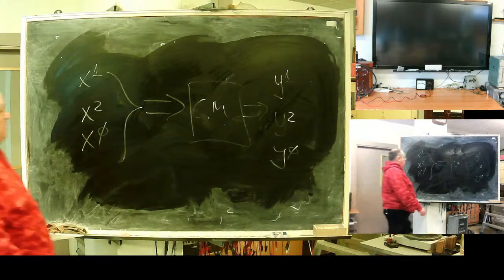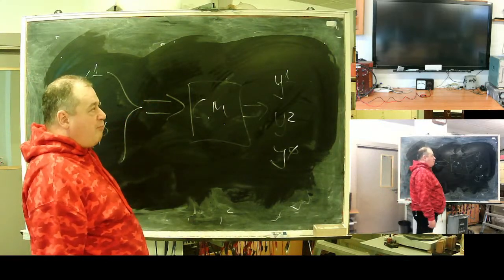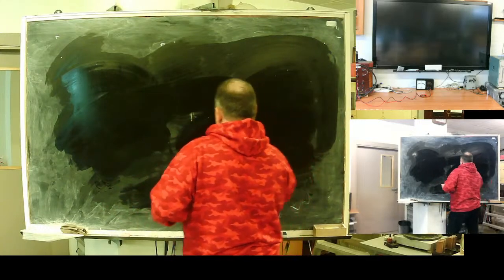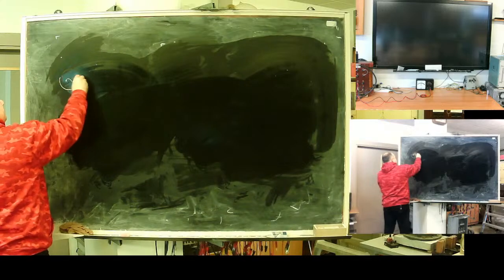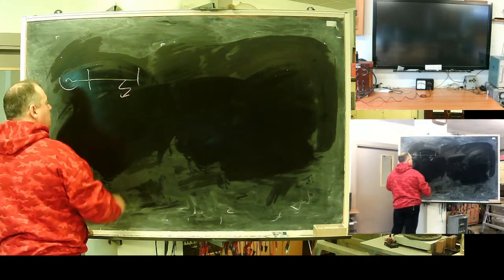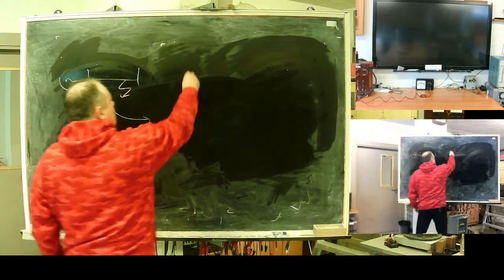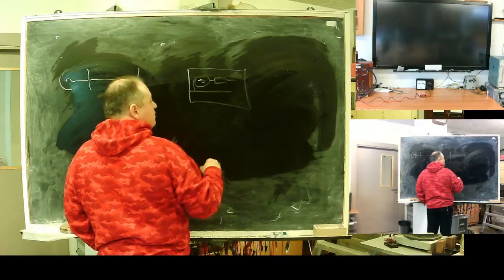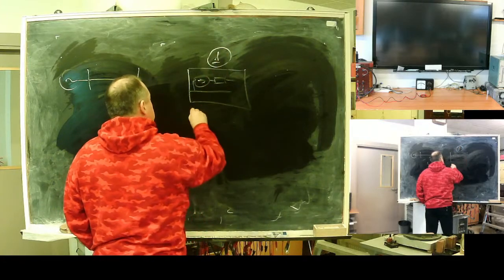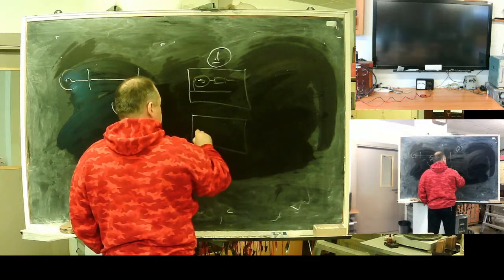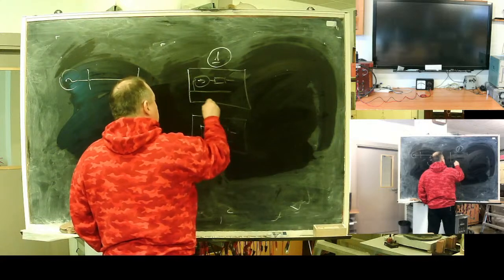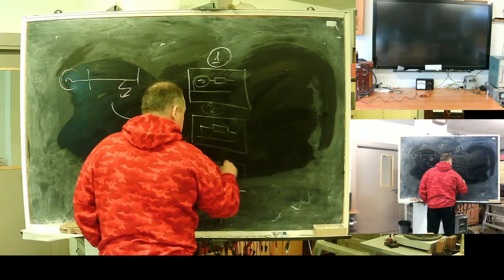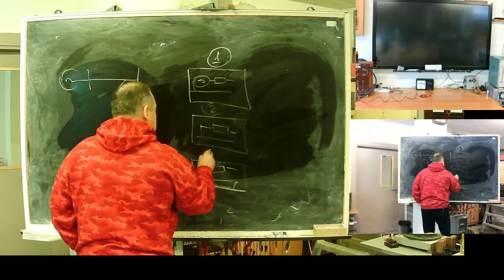Important is that in the space of symmetrical components, a real faulty line will be represented as an interconnection of three networks: a network of direct sequence, a network of negative sequence, and a special network of zero sequence.